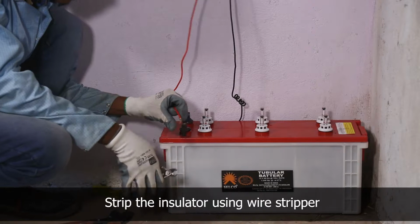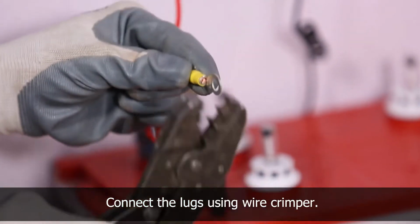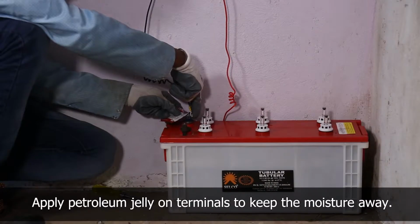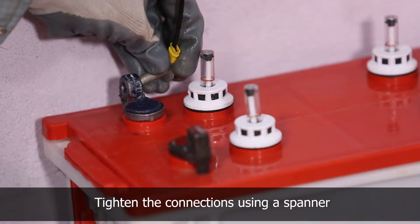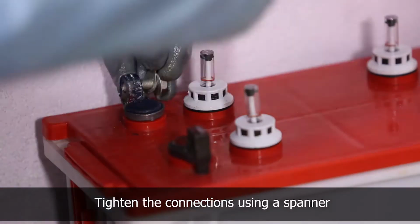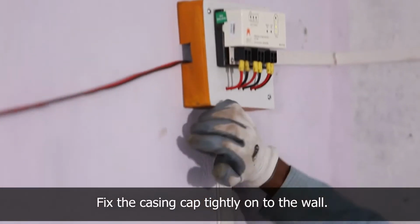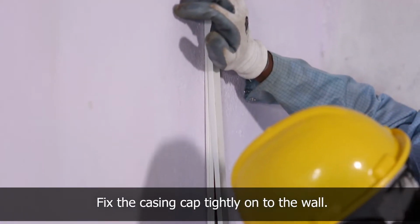Strip the insulator off the wire using a wire stripper and connect the lugs using a wire crimper. Apply petroleum jelly on the terminal to avoid rusting. After that, connect the wires to the terminal using a spanner. Red wire to positive and black wire to the negative terminal. Wires from the battery to the charge regulator is passed through the casing and covered with cap.